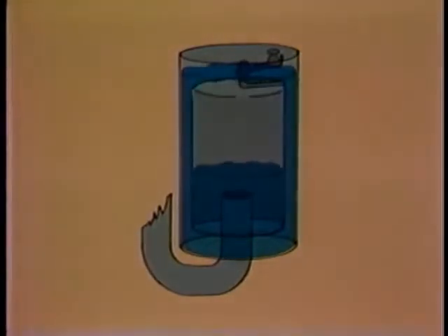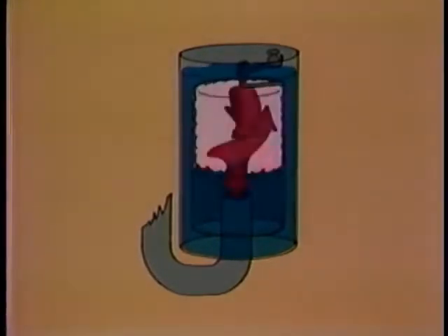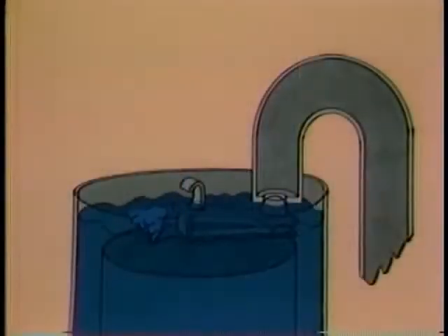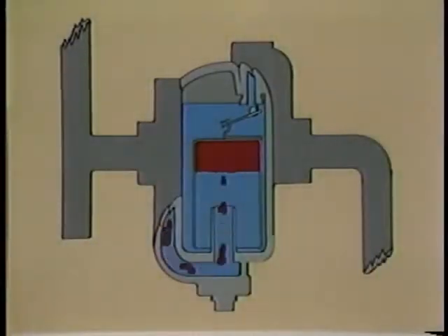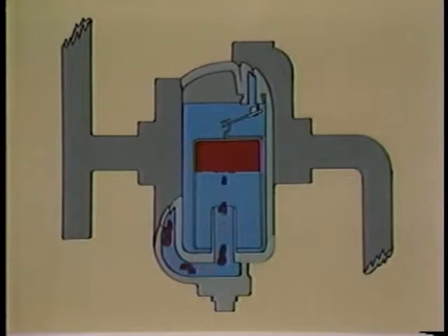This condensate provides a constant water seal above and around the bucket, preventing live steam from escaping from under the bucket. Finally, in the cap of the body is a space above the water seal where any non-condensable gases which have passed through the bucket vent will collect while the valve is closed. Incoming steam is trapped between the top of the bucket and the water seal below.